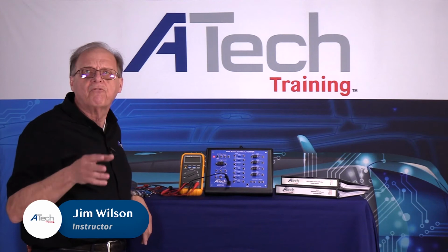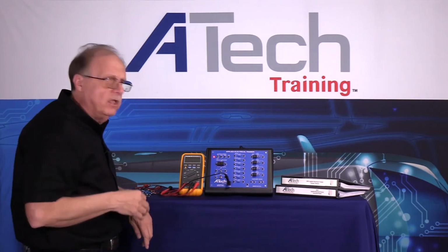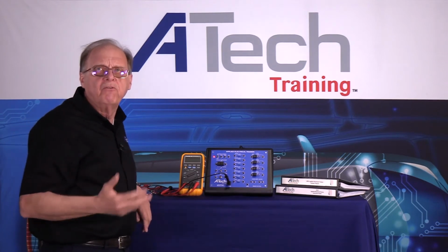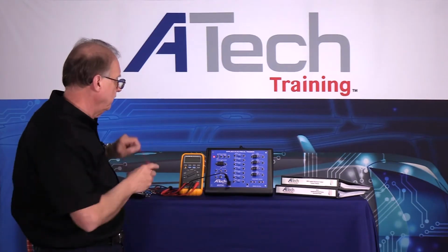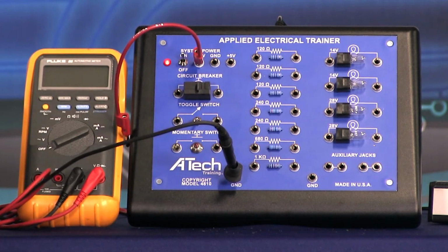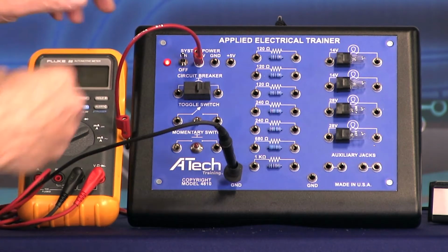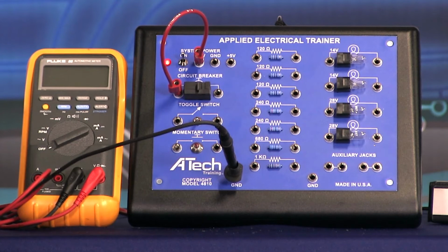I want to go out and start with a basic circuit that we'd see on a car. The basic circuit I'm going to build is a series circuit, and it might be the dome light on the car. First thing I need is 12 volts for this circuit. So I need to feed it through what device? My safety device. So I'm going to feed this into my circuit breaker.